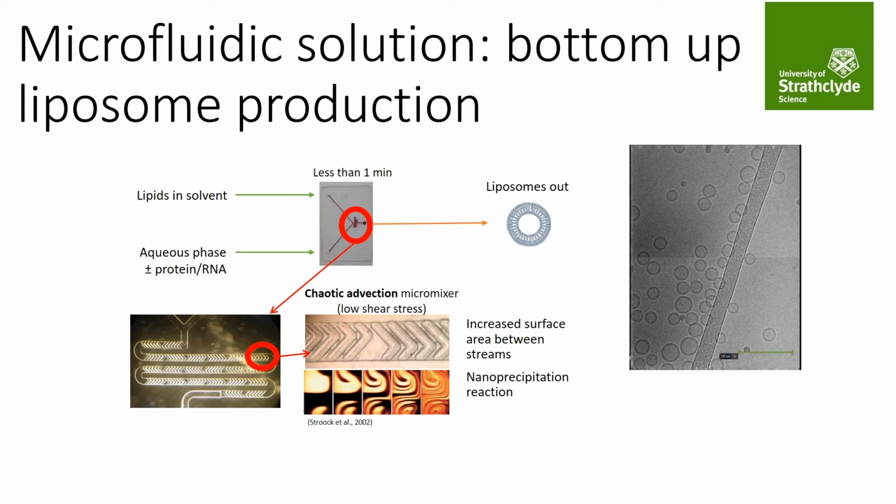And as they flow down the microchannels, the hydrocarbon chains within the lipids start to bend in order to reduce the contact with the aqueous phase, which causes them to eventually form vesicles. The flow rate of the organic phase and aqueous phase can be increased, which will lead to a more rapid dilution of the alcohol concentration, and as such, will reduce the time needed for the vesicles to stabilise, as there will be less fluctuations in the alcohol concentrations.